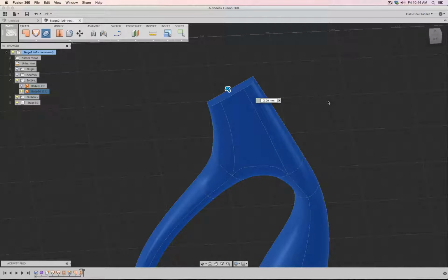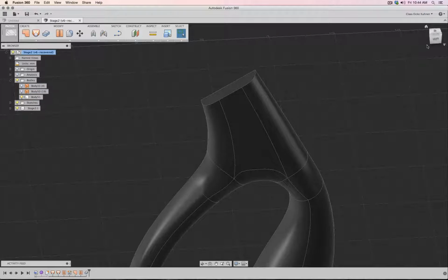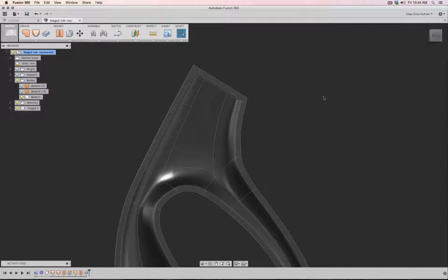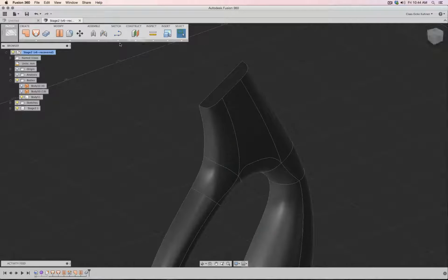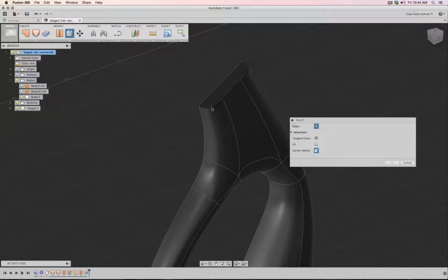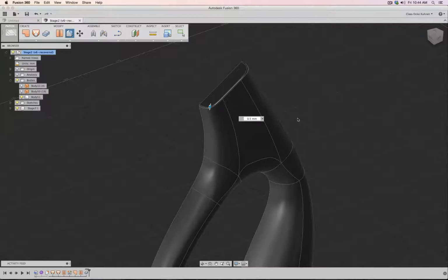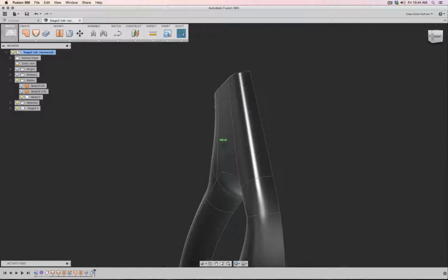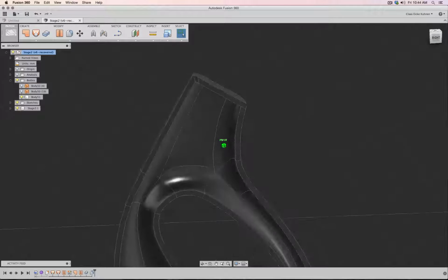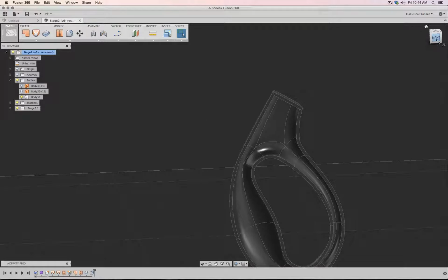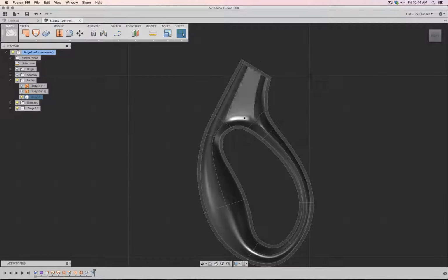The inside, the B surface, I don't really care about, because this is just technical stuff. So then there, here, 0.5 millimeter, just break that edge. Okay, there we are. And now I can continue putting in my blade, putting in the rib construction, etc. And then we can send it to the printer.